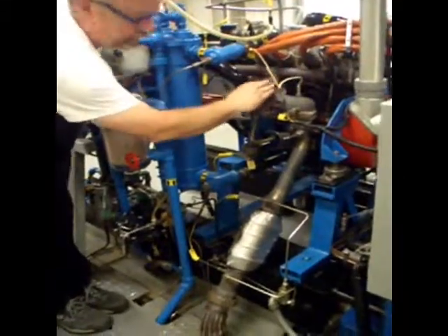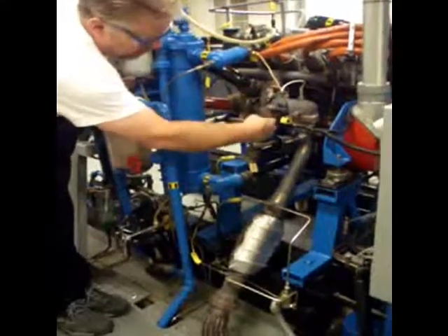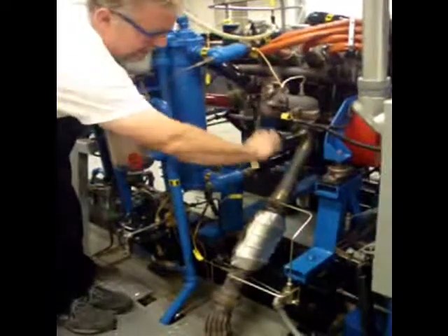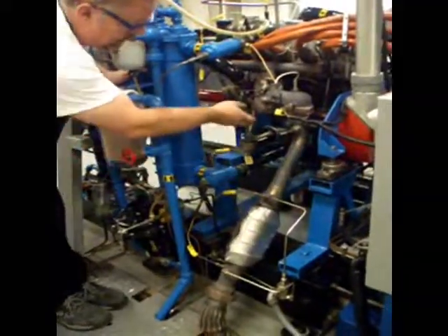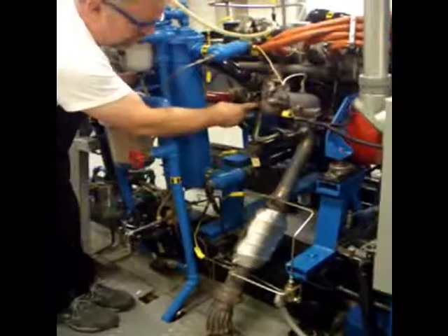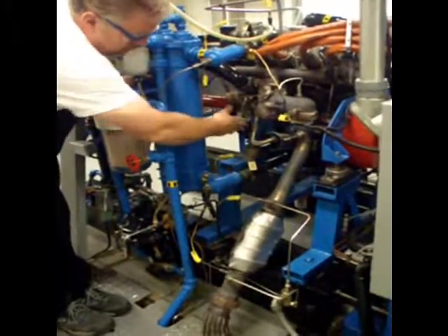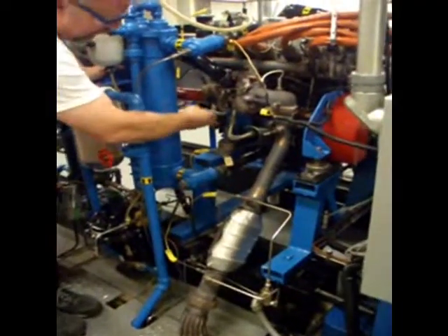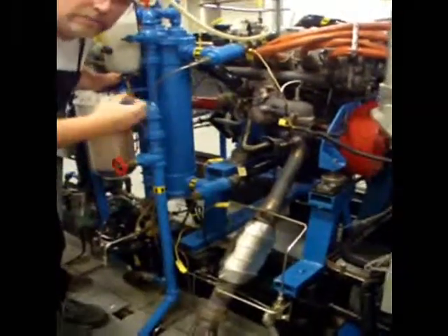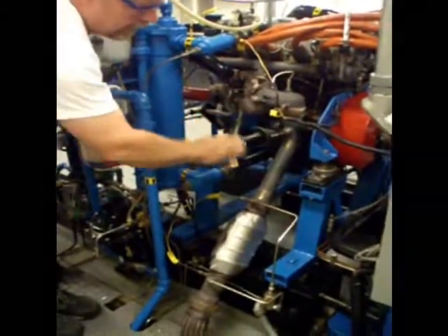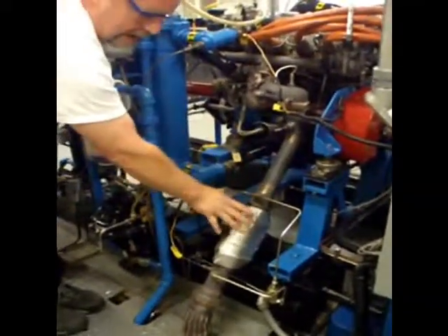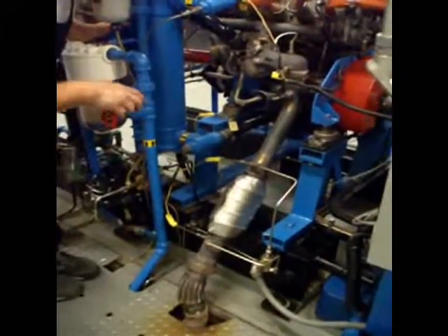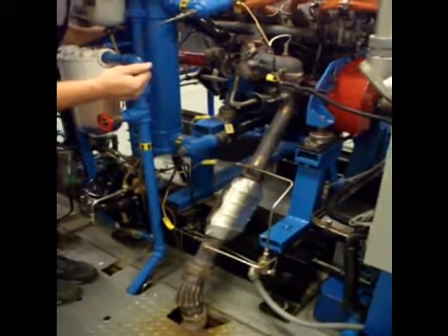As the exhaust comes through the exhaust manifold, it goes across the turbine of the turbocharger and spins a turbine inside, and then the exhaust goes out the tailpipe. That turbine spins a shaft inside the turbo, and it spins the compressor side, so the air that comes in is compressed and put out as a compressed volume. Following the exhaust flow, we have a catalytic converter right here. A catalytic converter is a device created to reduce emissions from an engine.